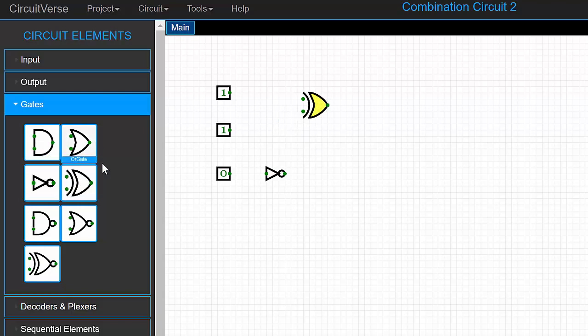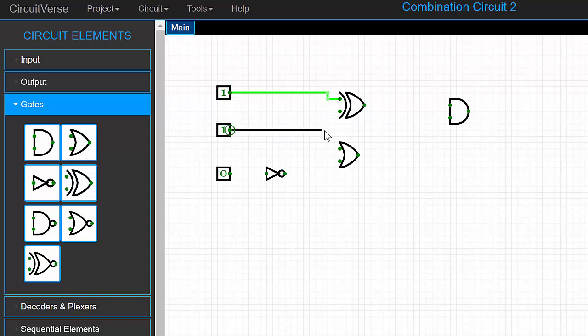I need an exclusive OR up here. I have an OR here, and then I have an AND gate over here. And so once again, my job is to wire this up correctly. So I'm going to just do that there. I also have one that comes from here and up and joins that together. I've got this input connected to a NOT, and then that comes out and joins into the OR. This one here also joins up to the OR. I just might fix that there.